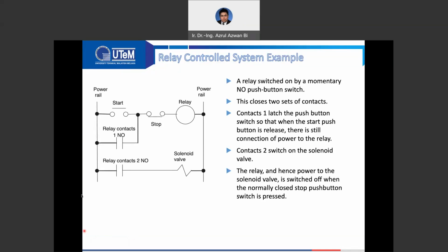If we have a relay, a push button start, stop, and somehow we latch this relay, then the relay will connect to the solenoid valve. Whenever we press this push button start, the relay will energize. Whenever the relay is energized, then the solenoid valve will be energized.